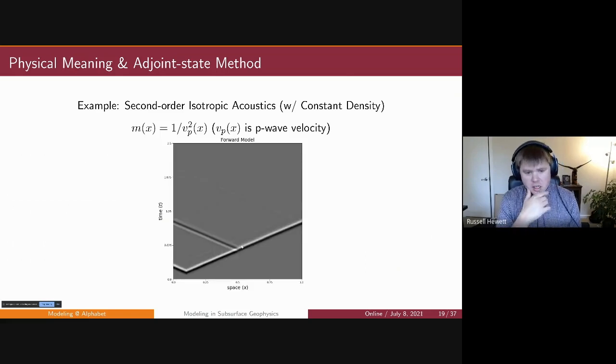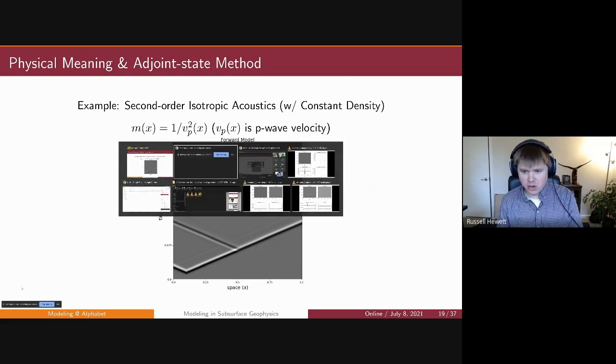You'll see a space-time diagram. I'm going to show the picture of it first so that you see what you're seeing as this assembles. This is the solution field as a function of time and space simultaneously. What you're seeing is the source injection here at the bottom left-hand corner and data propagating through the domain. And then I have absorbing boundary conditions that are not quite perfect, so you may see some further reflections off of the boundaries as time goes on. I'm going to show some movies of this and the next few steps in the process, and then we'll look at just the resulting images again to make that a little more concrete.